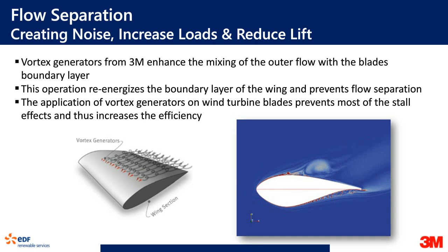So what a vortex generator does is enhance the mixing of the outer flow. When the wind comes and hits it, it creates controlled turbulence to reattach the separated flow, re-energizing the surface, getting more lift, and in turn more power as well. That's one of the key aspects for us.